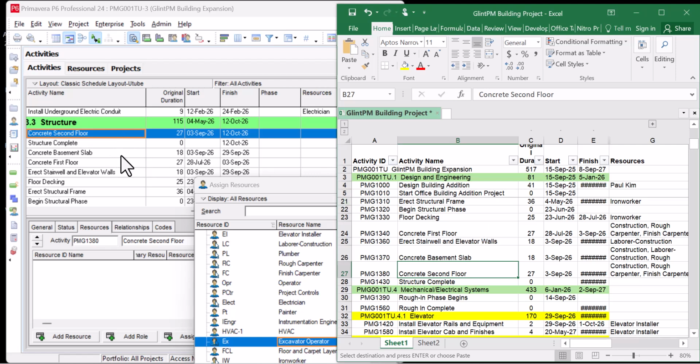We've already done the logic before now, so the logic will always supersede any other sorting that you apply. Assigning the resources will not affect anything as regards the logic, so I can still sort it the way I want later, either by activity name, duration, start, finish date, and other data of the schedule.